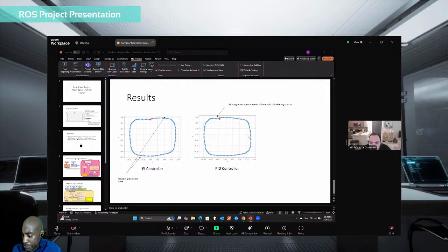So I think the reason this happens is from this little threshold of luck. What I mean by that is when and where the robot starts and exits this corner behavior. If we look here, we start here and we do this, and this one looks pretty nice. But if we look over here, it's a little different. It starts early, which means it's going to exit out of corner action later, or exit earlier, and then the regular logic will dominate, and that has relatively large effects because we're exiting at an angle relative to the wall that we don't want.